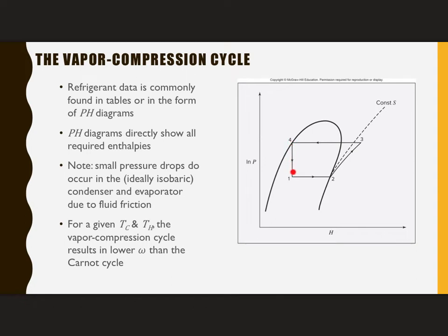And that valve, the expansion valve or the Joule-Thomson valve, whatever you are calling that device from 4 to 1, is a small device that has no heat transfer and no work because there are no moving parts. Really, you should design it so there's minimal to no change in kinetic and potential energy.